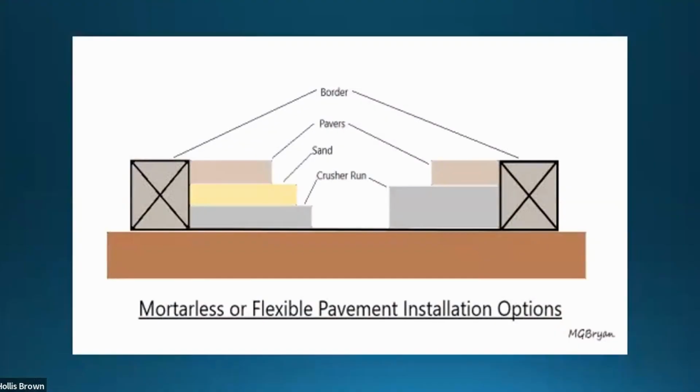This is just quickly touching on masonry for just a moment. And this is when you have pavement that's installed on just stone dust or something like that, the proper way to do it. When you put in masonry units on stone dust or something, you should really use a plate tamper and tamp them into place. You install the final product a little high and then vibrate it down into place.